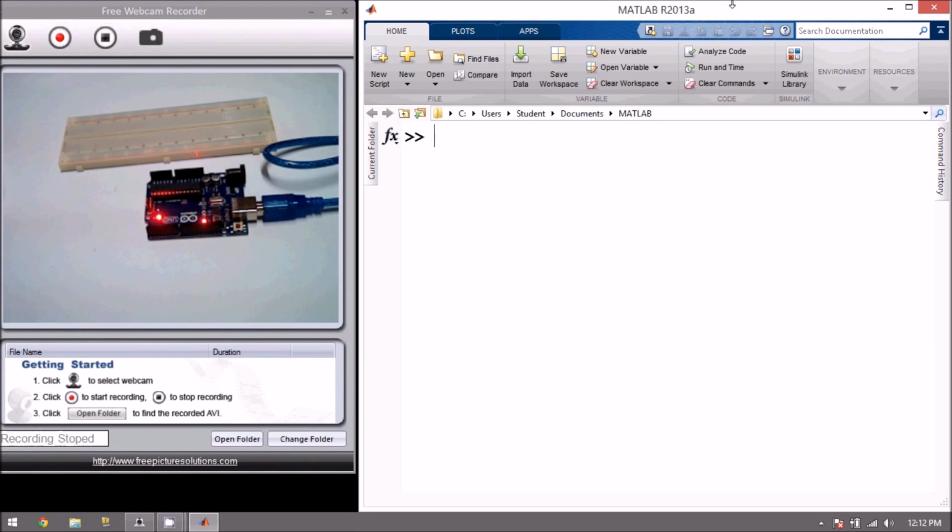Right, now let's start prototyping. Let's start with a very simple example where I'm going to connect an LED to the digital out of the Arduino Uno, and then light the LED on and off. So to do this, I need an LED. I'm getting a green LED and a resistor to connect in series with the LED. I'm getting a 220 ohm resistor and some jumper cables.